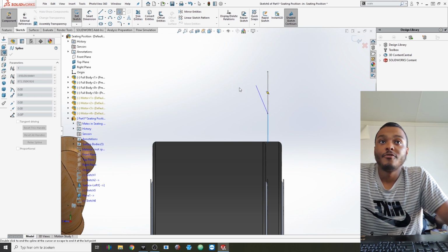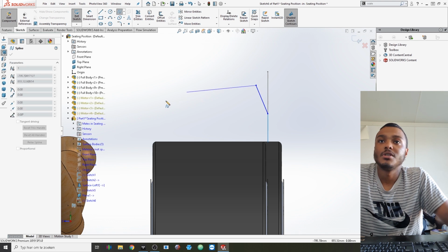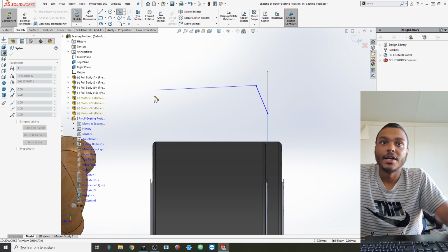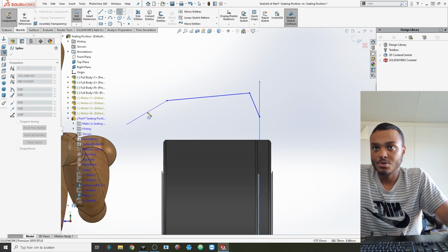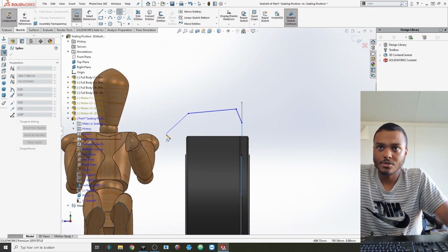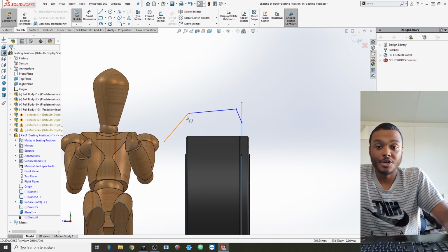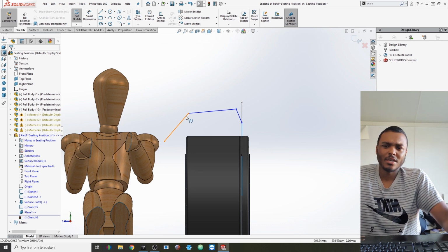So here we have the first point. I always cut these up into different pieces, because that gives you the opportunity to put sharper edges in these creases, and I always like the way that looks more than when it's just straight. So just continue to use the spline tool to drag these out, and here I use this point to give the space for if the wheel would be turning in certain cases. So in the rear you wouldn't really need it, but in the rear you want to keep the wide look of the tire.